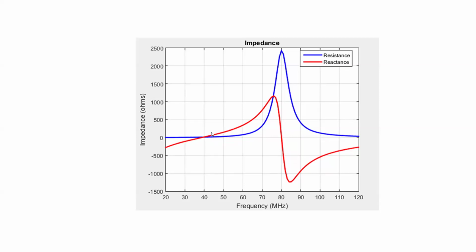You see that these two terms strongly depend on frequency. And I immediately notice 2 points, here and here, where the reactance is vanishing. So here and here, the stored reactive power of my antenna vanishes. So my antenna, here and here, converts the energy into propagating field.